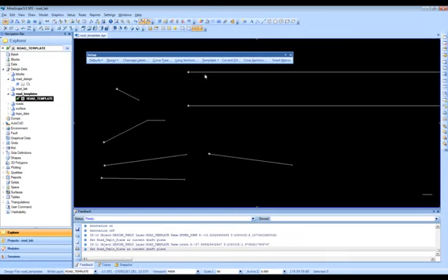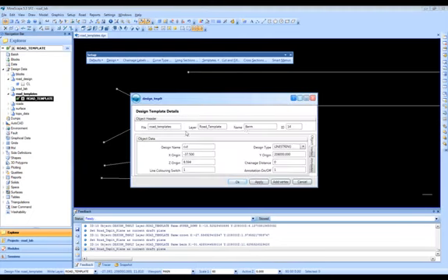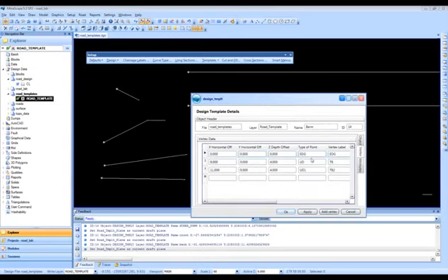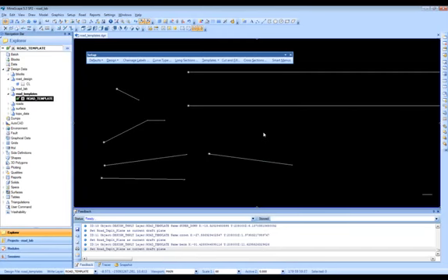So I've also just gone ahead and created what I call a berm template, and again, this will hook on to the edge of the road and then work up, and I specify two user-defined locations, which is basically the top of the berm here. So these are templates. Basically you define those, and then you're going to assign these templates to the generated road.